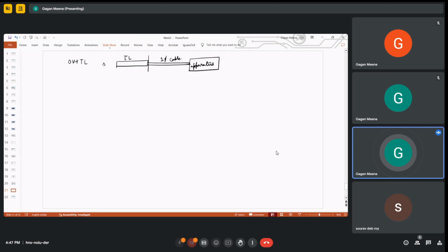So this is a single phase cable. And the characteristic impedances are 360 ohm and 120 ohm. A traveling wave of 165 kilovolts magnitude originates in the overhead line. So this is given as VA, and it travels toward the junction with the cable. We determine the energy transmitted in the cable during a period of 5.5 microseconds after the arrival of the wave at the junction.